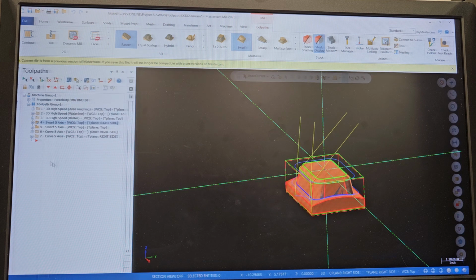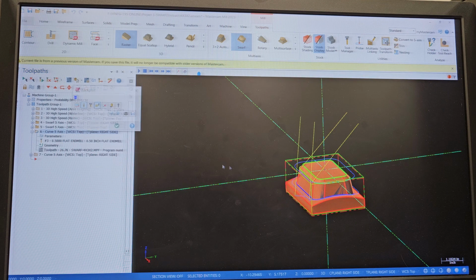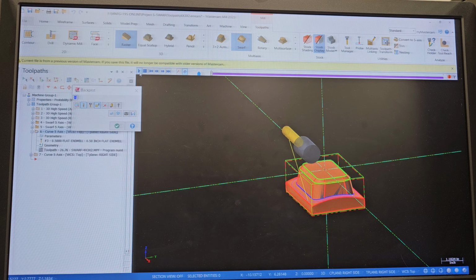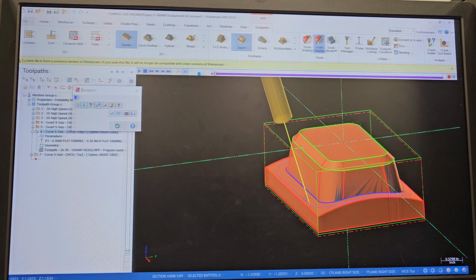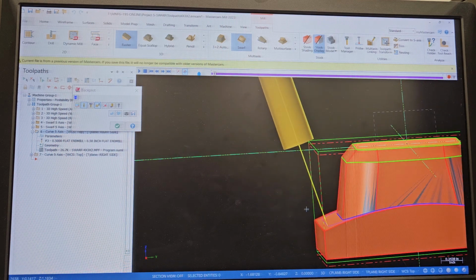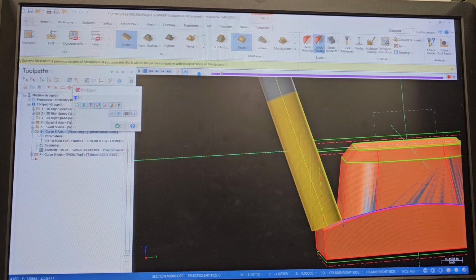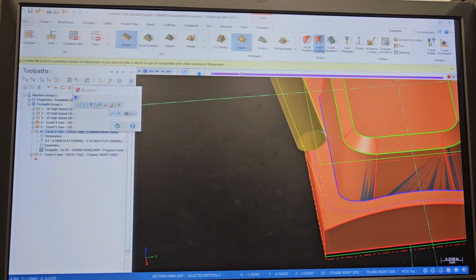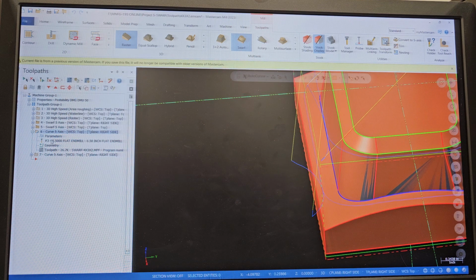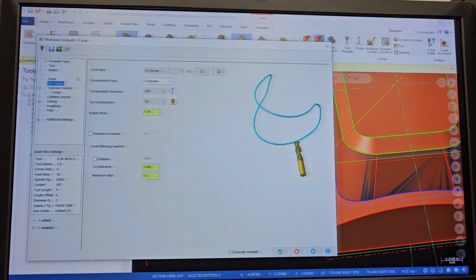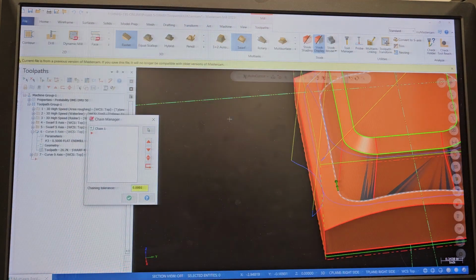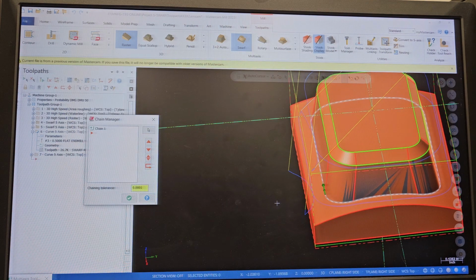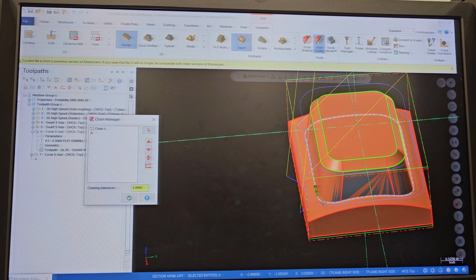So anyway, after we finish this, we're gonna use a curve toolpath, and that curve toolpath is gonna clean up the bottom. It's gonna clean up this guy right over here. We always use the curve toolpath. For the curve toolpath, you're gonna use this geometry right here. You're gonna use this curve down there. Okay, going in that direction.